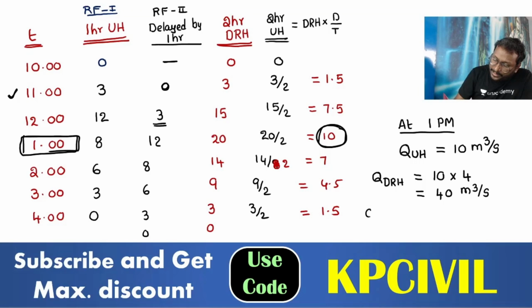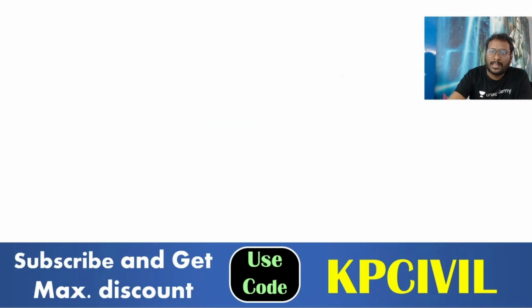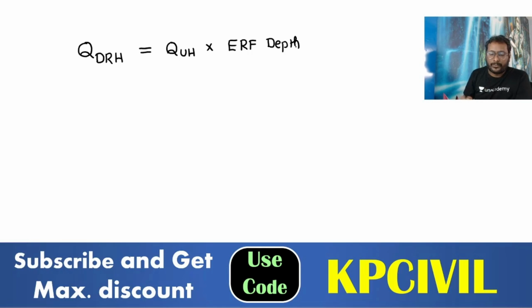And what is the flood hydrograph? Flood hydrograph is equal to direct runoff hydrograph plus base flow. I have given all the formulas, I think you remembered. Q DRH is equal to, I am writing again, Q DRH is equal to QUH into effective rainfall depth.